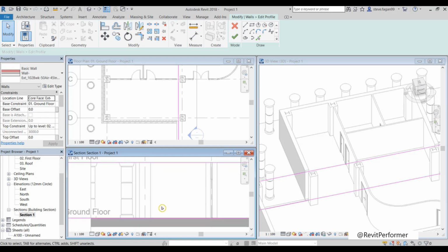Next, what I'm going to do is draw the opening myself. In the draw panel, I'll use the line tool to select the lower end and give a height of say 2200, attaching to the column and bring it back down.